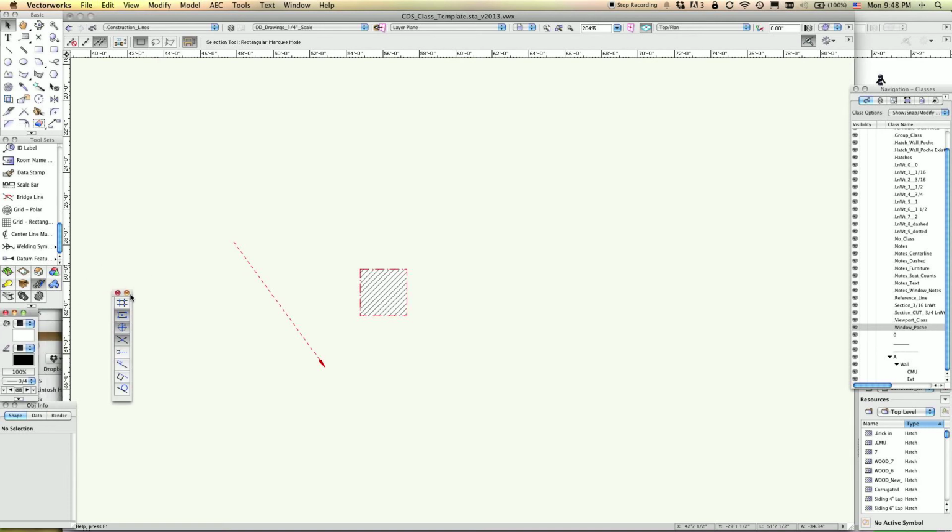This toolbar controls snapping. If I'm going to draw a line, I just hit the L button for line. It snaps because I've got these corner points. Here we go: snap to corner points, intersection. Right now, if I get close to the corner, it'll snap to the corner.